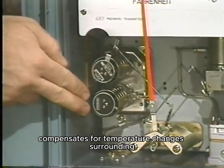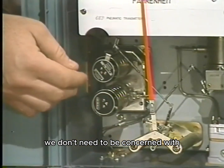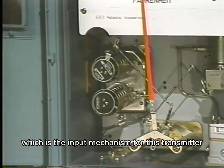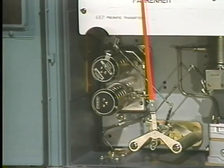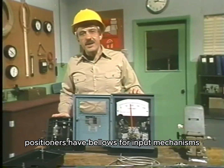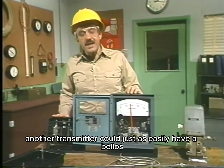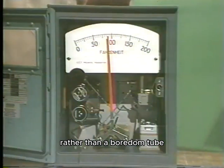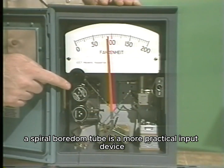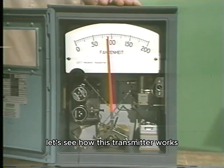This second tube compensates for temperature changes surrounding the transmitter, which for our purposes we don't need to be concerned with. Instead, we'll concentrate on this first Bourdon tube, which is the input mechanism for this transmitter. Now, I'm not suggesting that positioners have bellows for input mechanisms and transmitters have Bourdon tubes. Another transmitter could just as easily have a bellows rather than a Bourdon tube. But because of the design of this particular transmitter, a spiral Bourdon tube is a more practical input device. Well, let's see how this transmitter works.